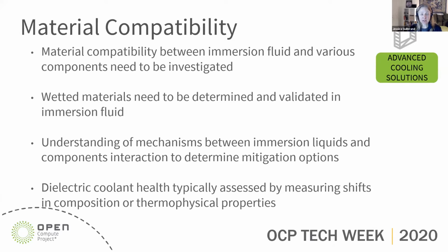So that awareness is fundamental as well. And of course, you also need to make sure that the health of the immersion liquid, the dielectric liquid, is maintained during the lifespan of your installation, by tracking the properties of the liquid to make sure there are not a lot of contaminants or other things going on that change the characteristics and potentially the capabilities of the solution.